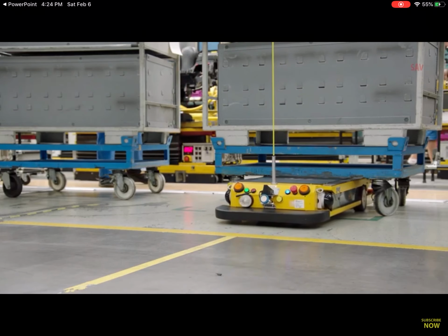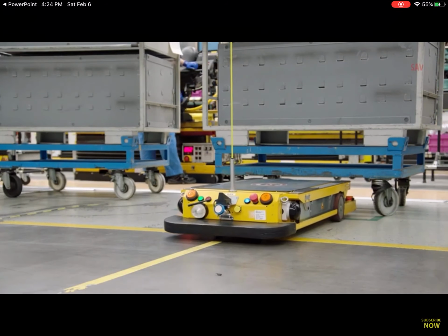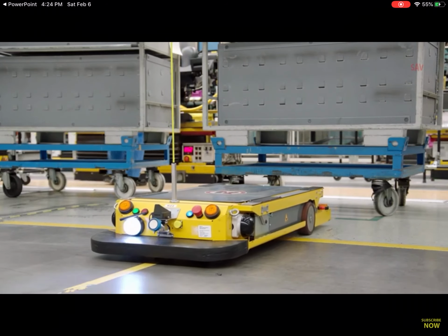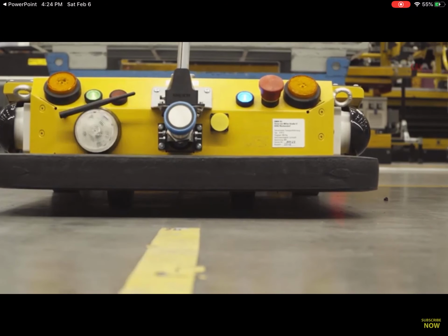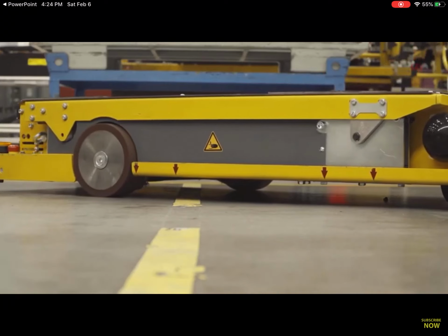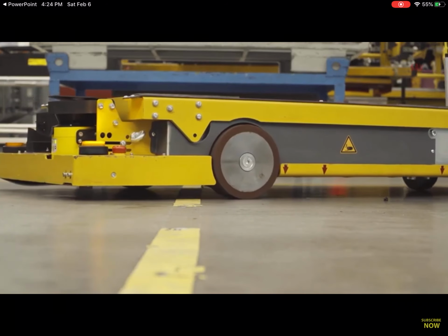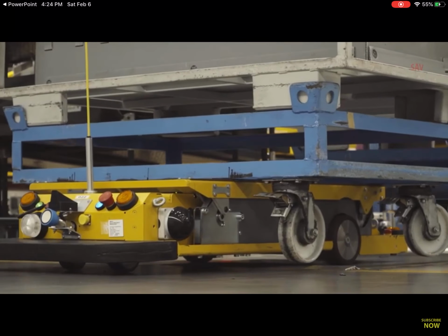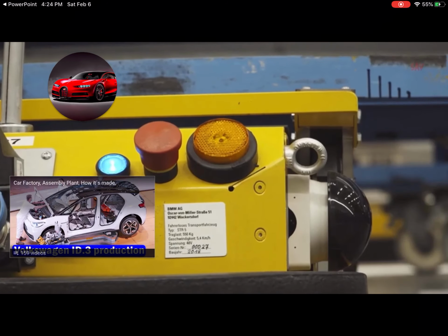So for controlling the AGVs, either you can use an onboard control panel. For example, this one has control panels. There are different buttons you can hit, or you can use some remote call stations. It can build some station at a certain place, and on that it has a control panel and controls the other AGVs, routes and transportation and controllers. And another one is you can use a central computer system to program and design all the routes. So that also works.